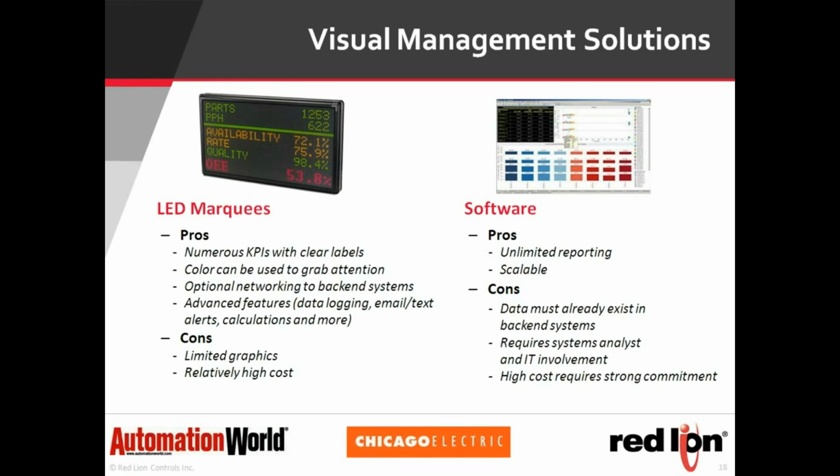Some of the cons is some of them aren't very good at collecting the data. Some of the packages I've seen are very good at getting data out of existing back-end MES systems. Others are great at crunching the numbers, but they have no means of getting the data off the shop floor, so then you have to integrate them with OPC communication servers to actually be able to get data out of PLCs or counters or timers that are on the equipment.